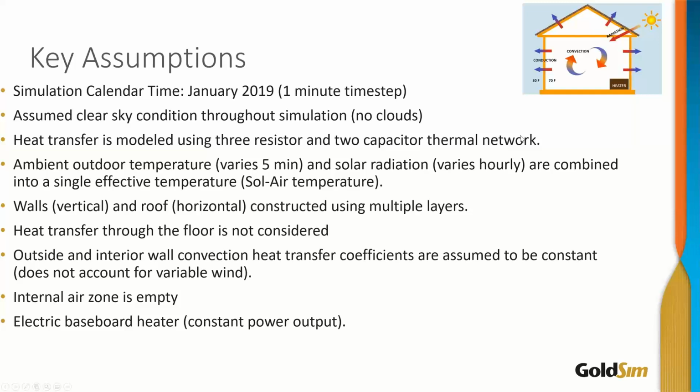and a couple of key input parameters and assumptions. The simulation goes for 1 month at 1 minute time steps through the month of January. Throughout the month, we are considering only clear sky conditions, so there's no clouds. And this clear sky solar radiation methodology is used to calculate the heat load for heating, ventilation, and air conditioning and solar applications.